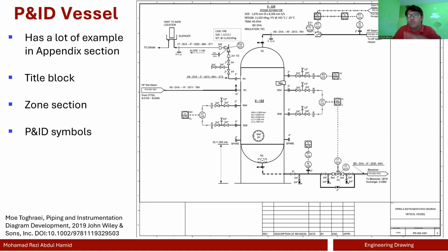Basically, it allows the fluid to go into the unit. But let's say, for example, there's a commissioning or whatever, and you want to close it. What you do is loosen the flange connection, and then simply rotate the number 8 such that the blocked circle of the number 8 will be blocking the pipeline. So these are called spectacle blinds.